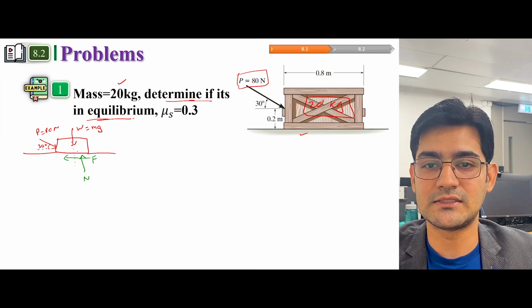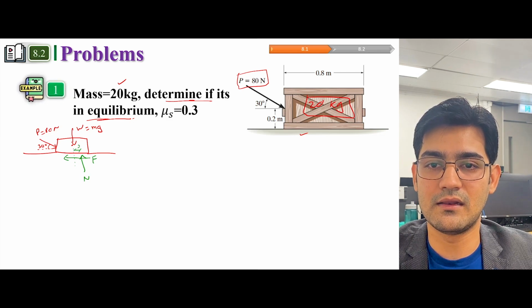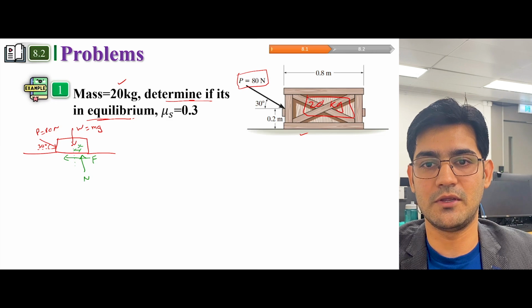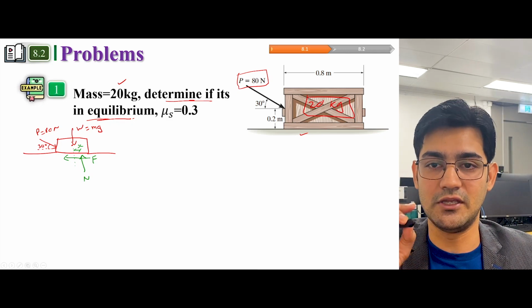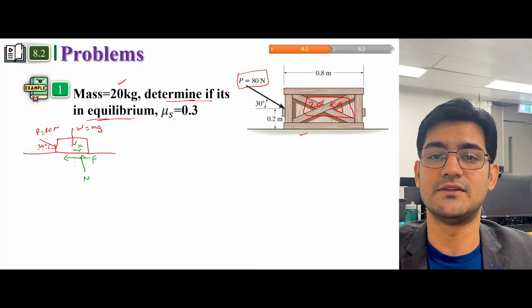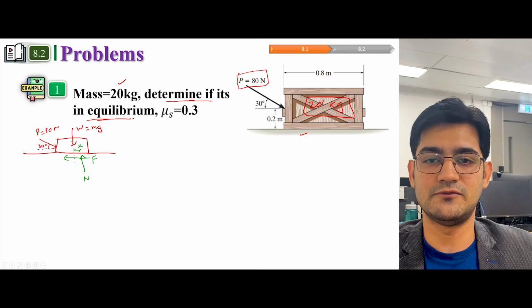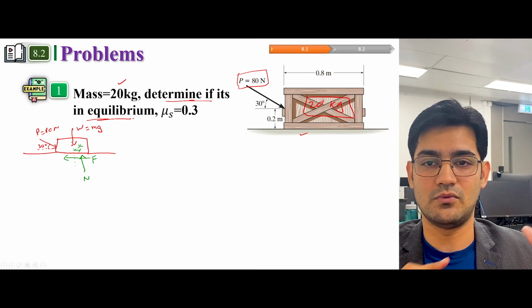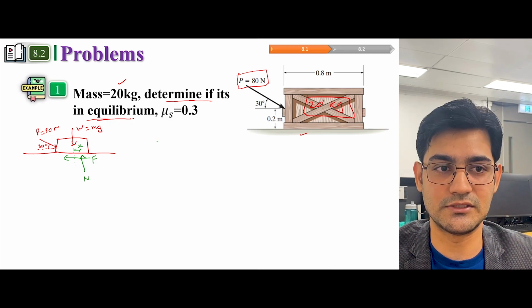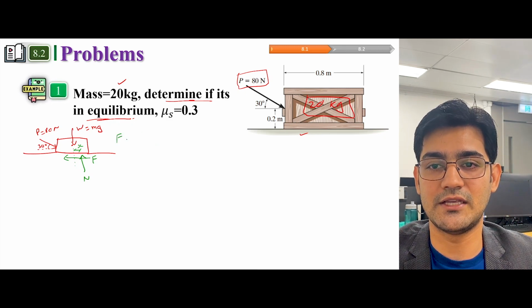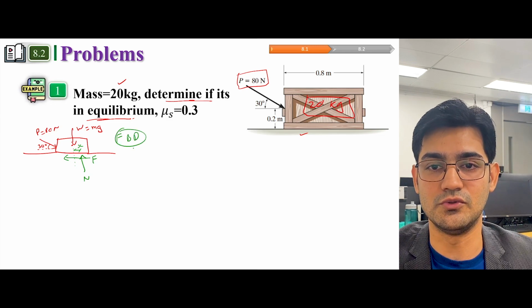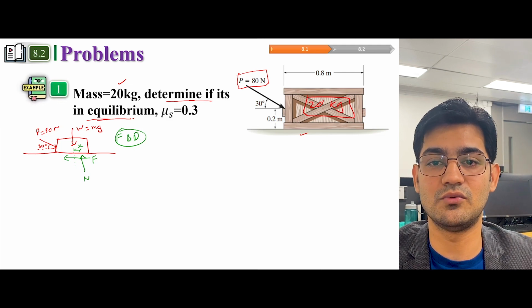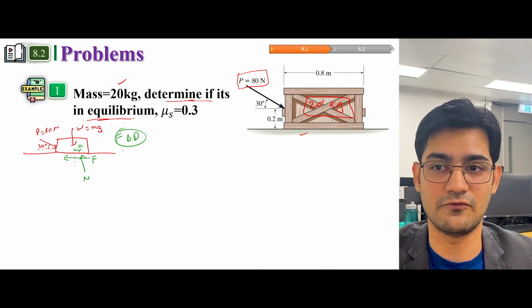Now as we discussed, this would be at some angle, because of those irregularities and because of the differences between the center of gravity and the distribution of the normal force. We'll have a reaction force at some distance, and that is also because we have to cancel out the moments as well, so we need to have it at some distance. So now we have a free body diagram. Once we have the free body diagram, we can then use the equilibrium equations and try to calculate all these forces, because now there are a lot of forces which are unknown.